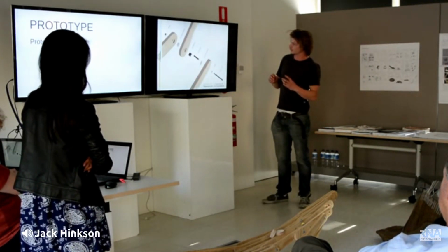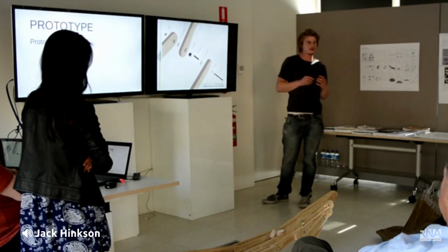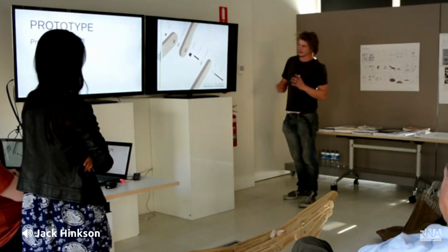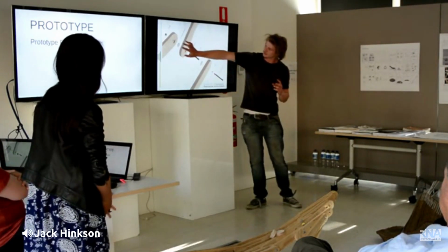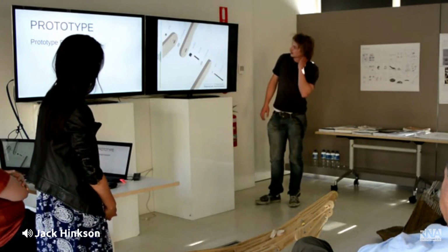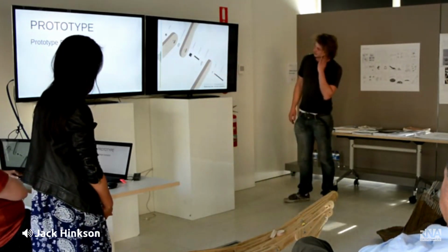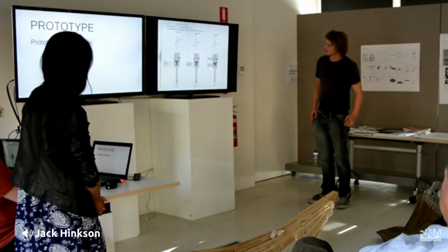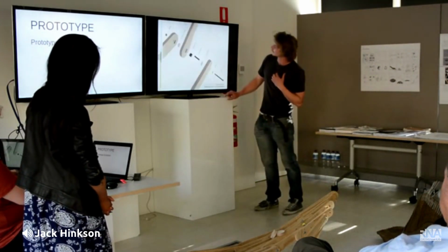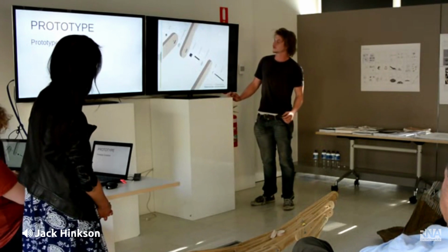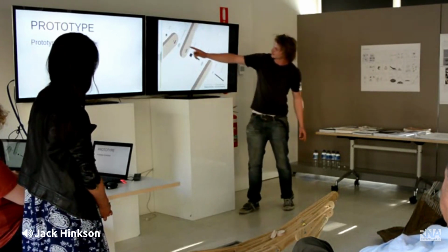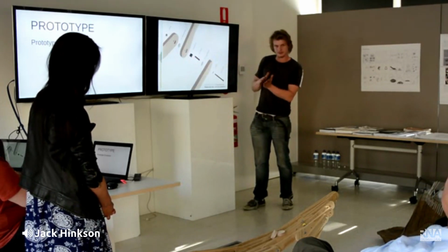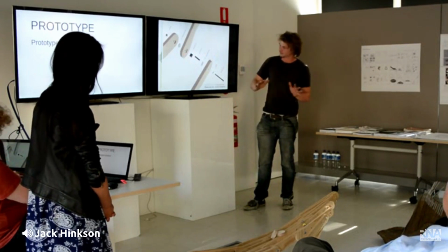We were also noticing that as we tightened the joints, there was too much friction, which was dampening our movement. So we introduced little slip washers in between the elements, and then we've got the compression rubber and the steel pin. There's one other detail which Rachel touched on earlier. This little pocket here is to accommodate the bulging of the rubber as the pin compressed it down, to stop the elements from splitting apart.